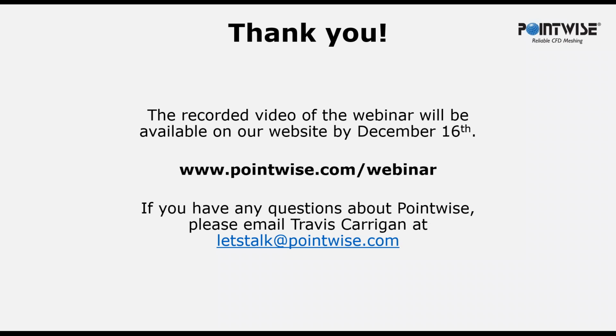I agree with you completely here. My recommendation for a triangular mesh is typically to keep the area ratio under 4 if possible. My recommendation for quad dominant meshes, because you can have a triangle next to a quad, is to typically keep that area ratio under 8. And Travis reiterated that and showed you this as well in his example.